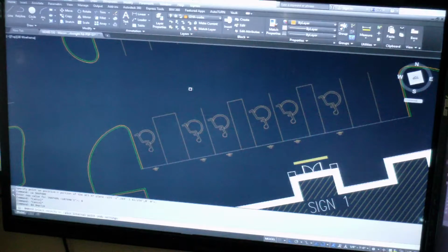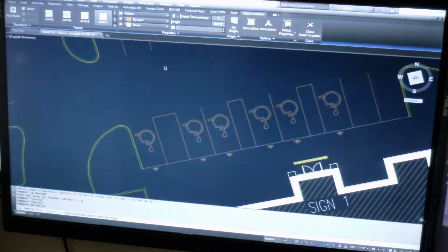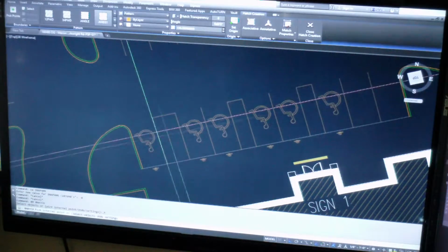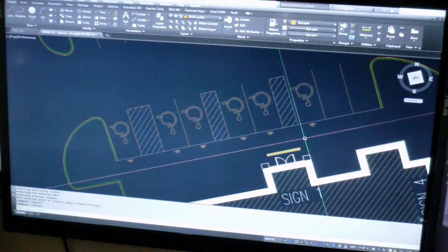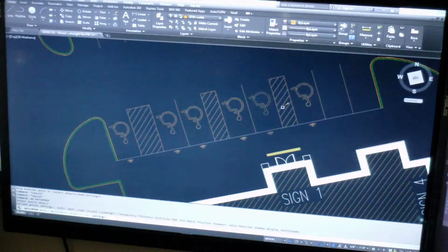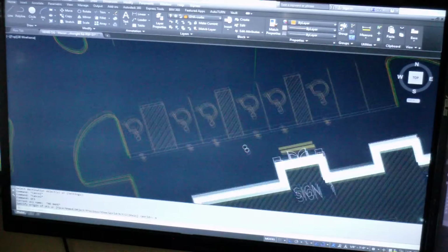So now I can create a boundary hatch, and it will think that way is up, and it'll be aligned with the space. I'm just going to use ANSI 31 at a scale of 150 and just pick points in here like that, and then match them to that. Now I can change my UCS back to world.